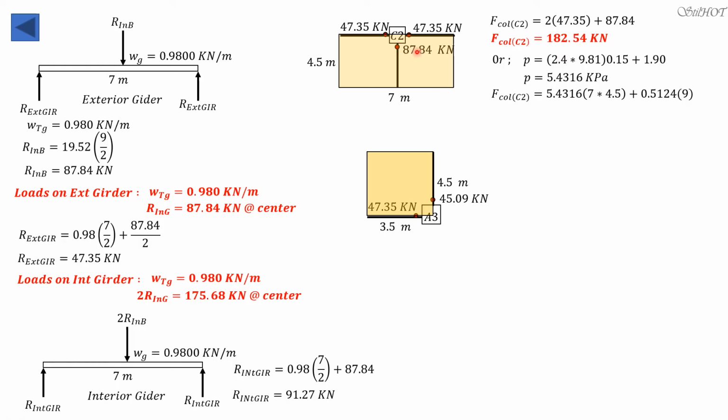In other words, this is 4.5, and since this is only half of the beam and the other half is distributed there, half the weight of a beam of length 4.5 plus half the weight of a beam of length 4.5 adds up to one whole beam of length 4.5. So it's just like there are two beams of length 4.5, making 9 meters of length.